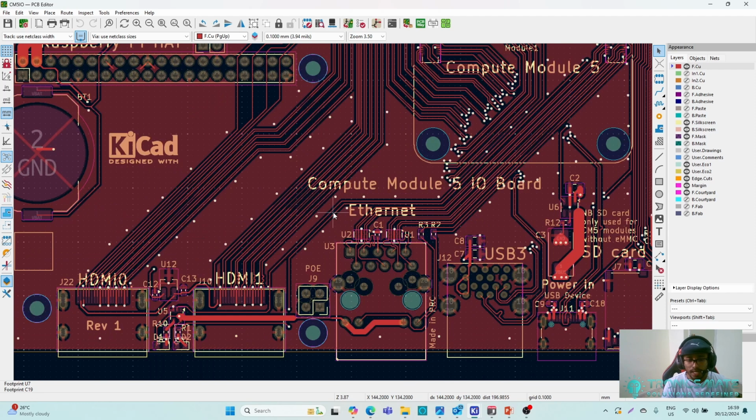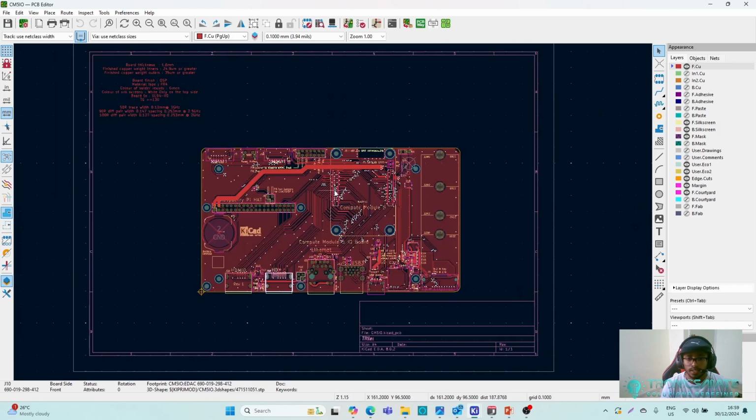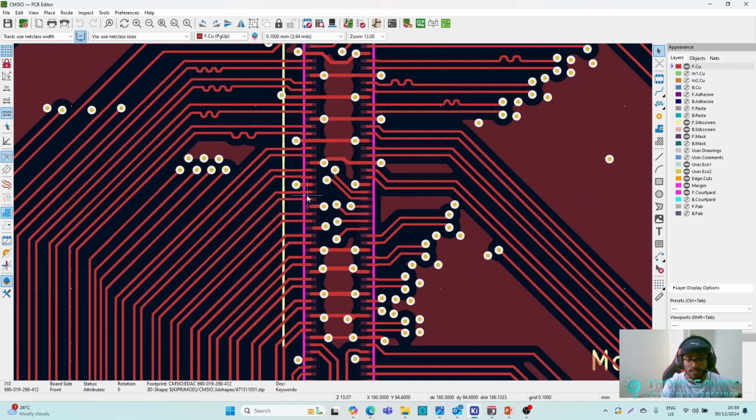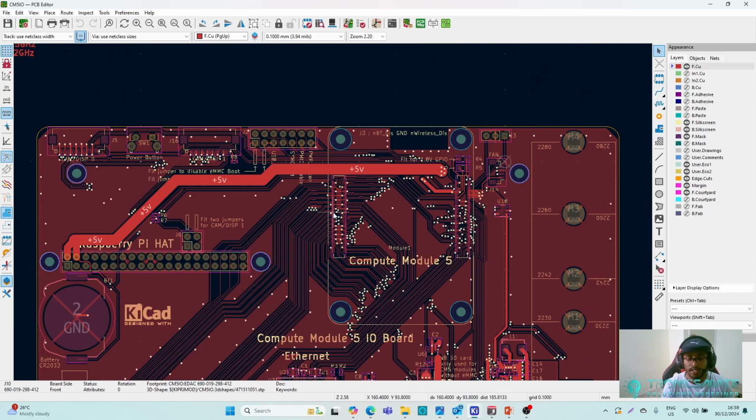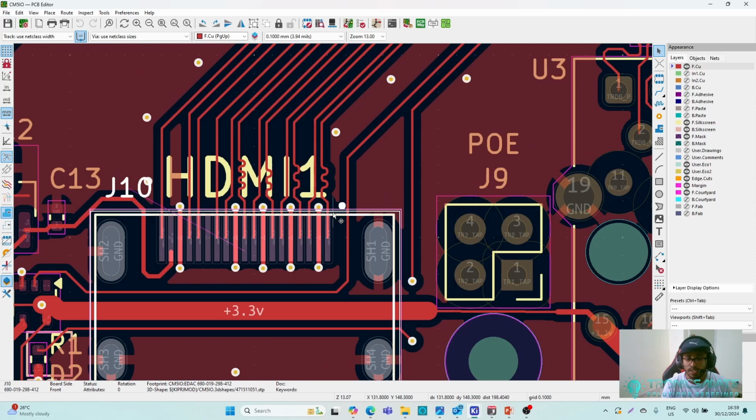So we should do impedance matching for these signals. Otherwise, if the impedance does not match, the signal gets reflected. Let's say you transfer the data signal here, and at the receiver end you do not receive that power.